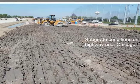And if you look closely here, you can see that this, I think this was an 815, isn't walking out of the clay. That's usually how you get a visual on whether or not this material has been compacted into a stable condition. The machine will walk out. And it wasn't doing that, it was just wet.